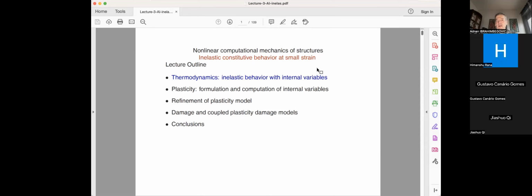The difference to elasticity, either linear or nonlinear elasticity, is that you actually have to take a very precise definition of your loading program in order to define what exactly would be the final state. Namely, it is not the same if you're simply loading in one shot or if you're doing several cycles of loading and unloading. Even though you find yourself with the same stress state at the end, basically you will definitely not have the same plastic deformation which gets accumulated, because several cycles of loading and unloading could certainly lead to much higher plastic deformation.